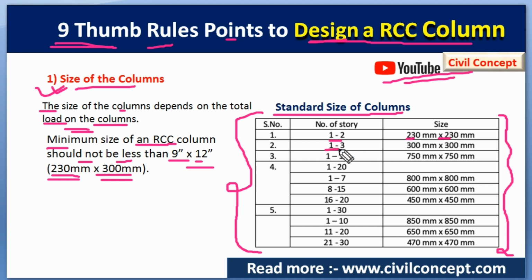If we are constructing up to 3 storeys, then we can provide the standard column size of 300 mm by 300 mm. If up to 10 storeys, then we can provide 750 mm by 750 mm. But if we are constructing a building up to 20 storeys, then from 1 to 7 storeys we can put 800 mm by 800 mm as the column size. From 8 to 15 storeys we can provide 600 mm by 600 mm, and from 16 to 20 storeys we can provide 450 mm by 450 mm columns.